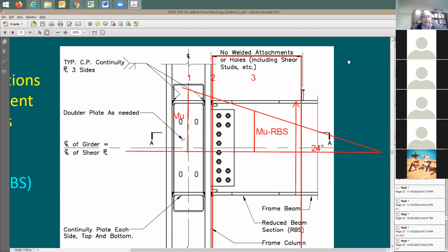So I was just wondering, we put the continuity plates so that the flange of the column doesn't bend. That's due to tension in the beam. Tension or compression, yes, but mainly tension. Is this tension or compression usually in the beam flanges only, or in the beam flanges and the beam web?